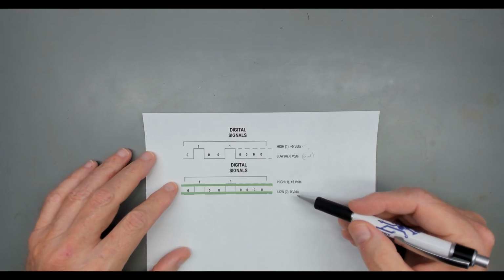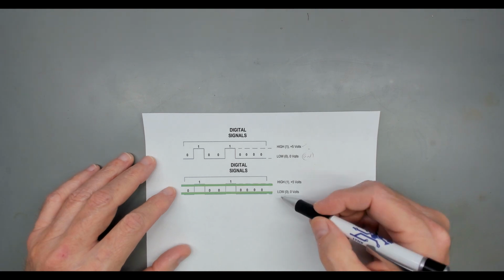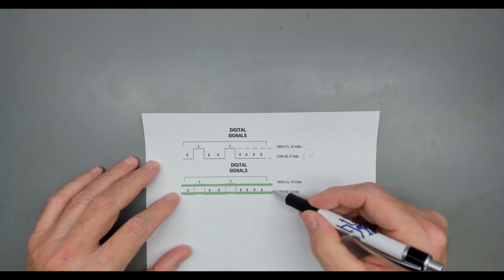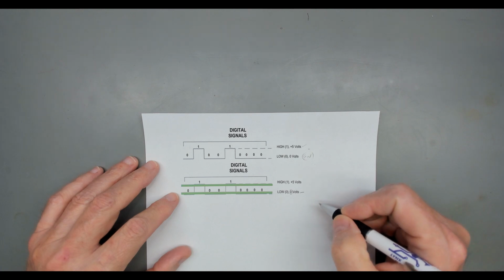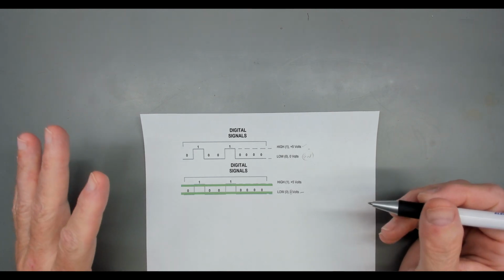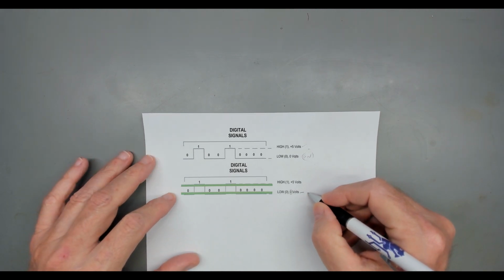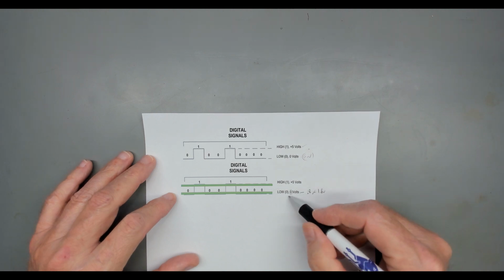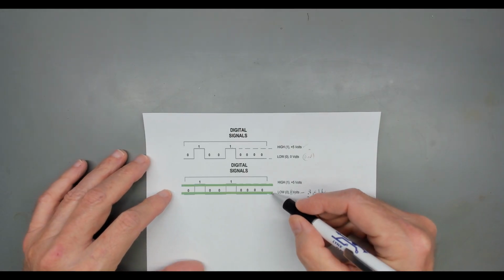If we look at the second set here, the only difference you're going to notice is there are 2 green bars. And what I'm trying to signify to you here is that 0 is a range of voltages. It's not 0 volts. It's 0 to some volt. And the old TTL logic, it could be anywhere from about a diode drop to about 2 diode drops. So some stuff was 0.8 volts, some stuff was like 1.6 volts. Between 0 and somewhere in here on the older chips, different chips are different, things would be considered to be 0. So you have a range of 0.